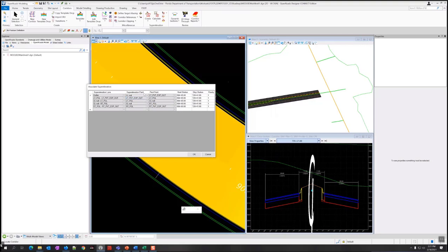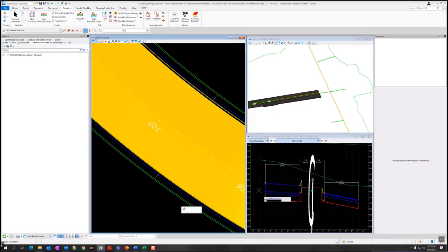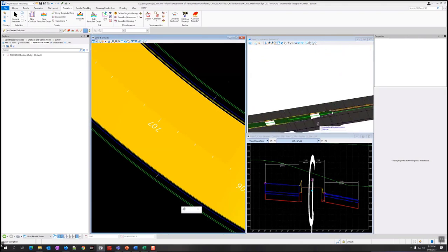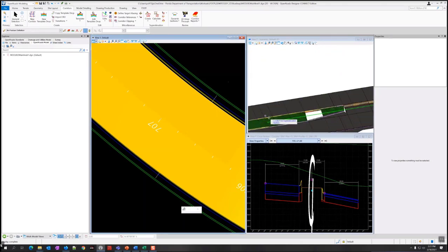It's going to give us an error that we have it super elevated twice because I already have this elsewhere, right? That's fine. Let's not worry about that. It just won't be super elevated properly until we fix it. So I'm going to click OK. See, it says error recursive super elevation control added but not enabled. So we'll fix that. So I'm going to click OK. It's going to reprocess. I made some changes. Some things look weird. Don't worry about that right now. That was to be expected at this point in time.